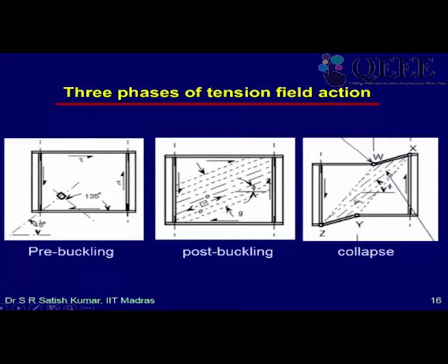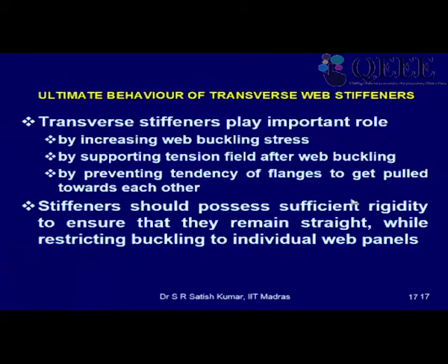Okay, so we will only have to calculate the critical buckling stress, tau critical, using the formula, and that is for an ideal plate. So we'll have to convert that into tau b for a practical plate. Similar to columns and beams, plates also buckle at stresses lower than what is given by the theory. So that we have to incorporate. We'll see how to do that.